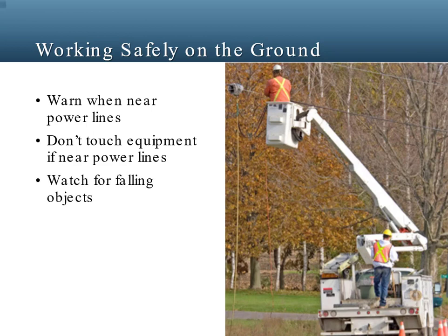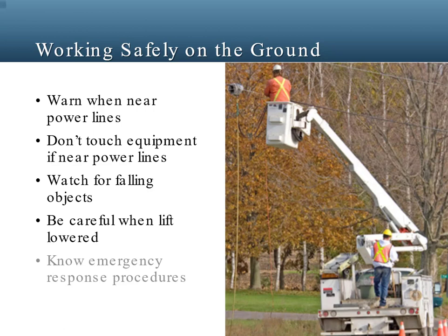Watch out for falling objects such as tools and materials. Always wear a hard hat to protect your head when working on the ground near an aerial lift, and never stand directly under the lift. Also, watch out for the boom and lift when the lift is lowered to make sure it doesn't come down on you. The operator will be looking out for personnel on the ground, but might miss someone because of a blind spot. Finally, make sure you know emergency response procedures in case the worker in the lift is injured or can't operate the controls.